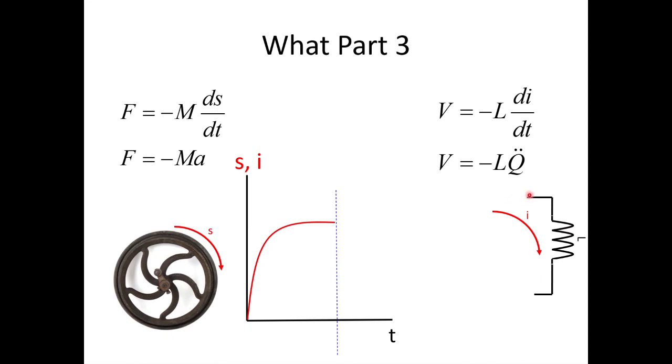If instead of shorting the loop, you open the loop, not allowing the current to go anywhere, the voltage across this inductor could be hundreds or thousands of volts, because that inductor is going to try to keep that current going. This is what they call inductive kick. This is used to make cattle prods and zappers and all kinds of high voltage sparking, arcing devices. Again, I didn't update these models for this case here.